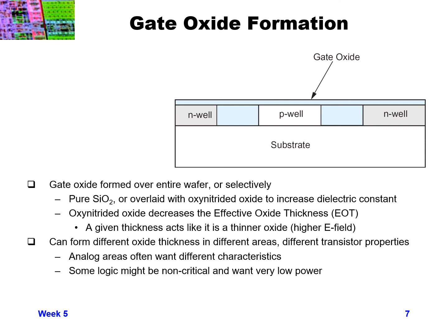So you have a measured thickness, but the measured thickness acts like it's a thinner oxide, and in fact you can get a higher electric field than you would normally predict based on the thickness. And so since you have a physical layer that's a little bit thicker, but it acts like a thinner oxide, this allows you to get a little bit less leakage through the oxide.